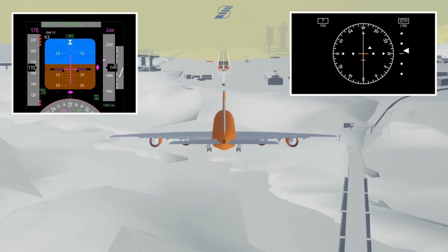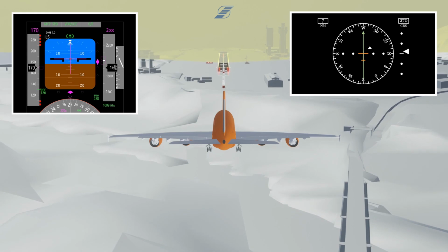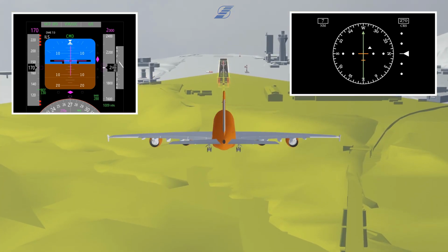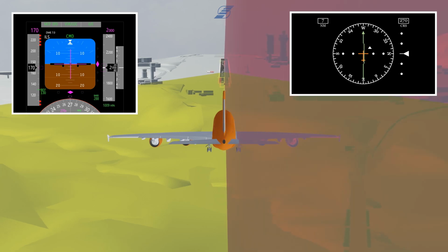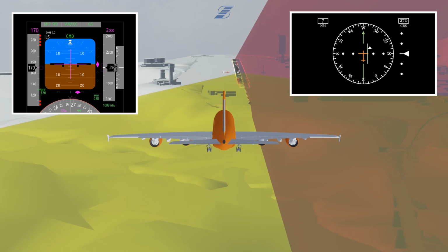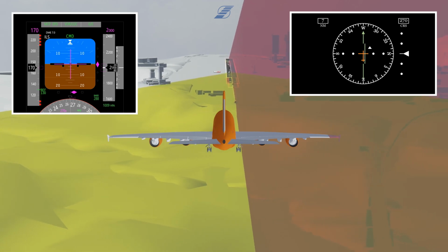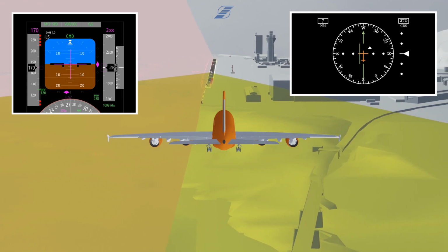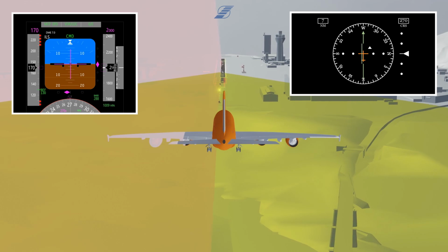Once beneath the ideal glide path, both pointers swing in the other direction, true to the saying, always fly to the needle. Flying left leads to a deflection of the marker in the PFD beneath the artificial horizon, and simultaneously the deviation bar of the HSI moves to the right. Getting right of the ideal localizer beam, both indicators move to the left.